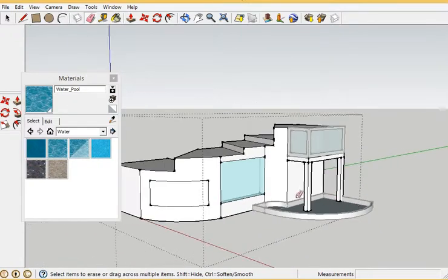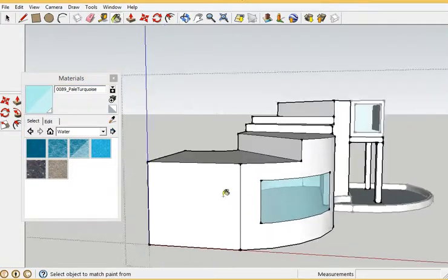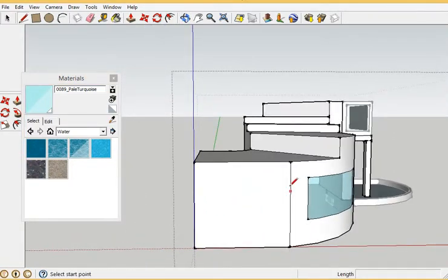Now, if I rotate 90 degrees, it will snap. It will try to snap to 90 degrees, and every 90 degrees it'll snap. And then left click a third time. Now, this was rotating around the blue axis, but we can certainly rotate around any other axis.